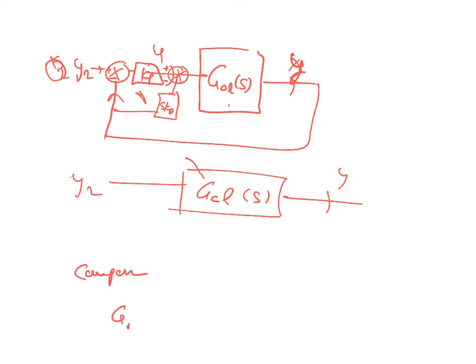So you have a desired characteristic equation, the denominator, the desired closed loop, and you compare it with your closed loop coefficients. Just compare coefficients, and basically you can choose your Kp and Kd.